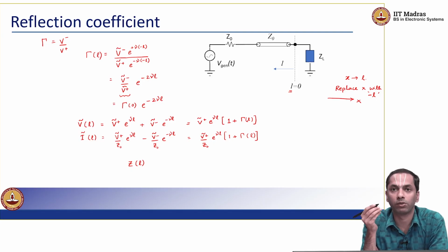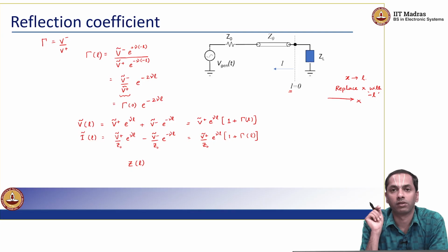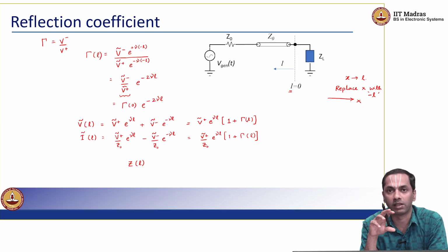So the amplitudes of oscillations for the voltages and currents are actually changing along the transmission line, just as we saw in the video for the beam bending, right? We noticed that there were locations where the beam bending was large, locations where the beam bending was small. So we are saying that the amplitude of these fluctuations in voltages and currents is now dependent on the position along the transmission line, which means that the ratio of voltage to current along any point along the transmission line is actually changing, right?